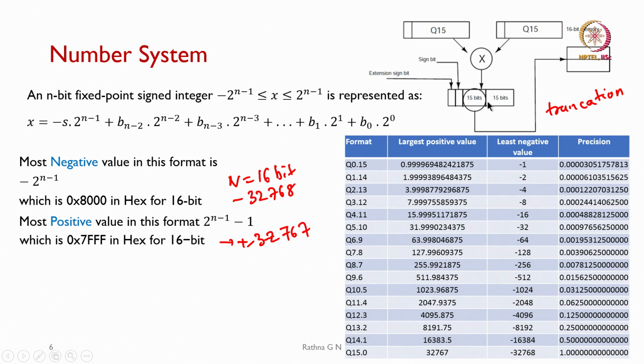Then I consider my 14th bit, and if it is 1, I can add 1 to this and then store the number back in the Q15 format. In that case I will be accounting for additional computation, which we have to pay for, otherwise the simplest one is doing the truncation. So, proper care is taken so that the results are within these higher bits.